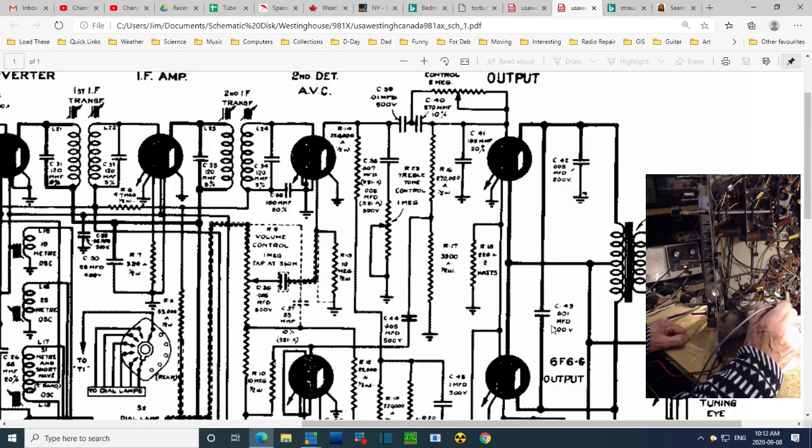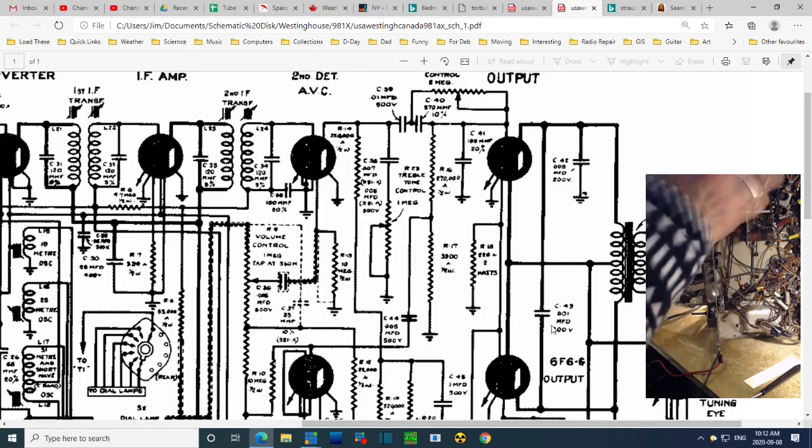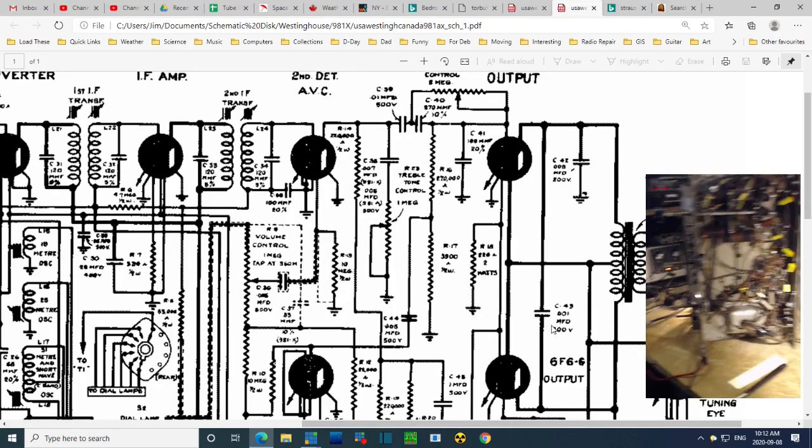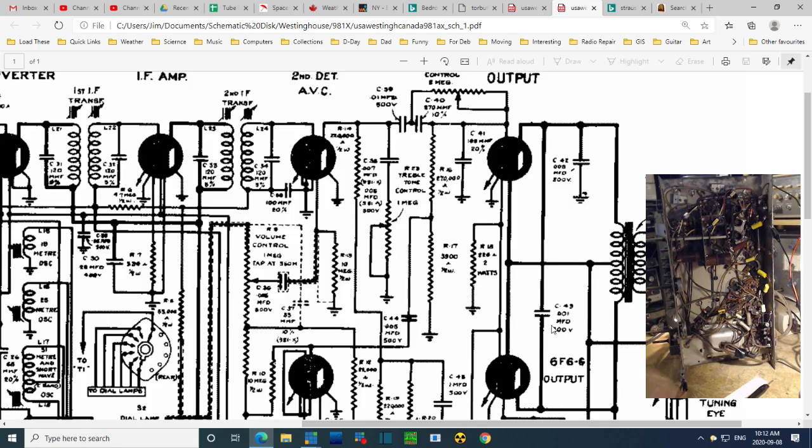Yeah, that's a rectifier tube at the bottom anyway. So either that tube, I could swap them. Yeah, swap them and see it. Hey, bingo! Swap those tubes. See if the voltage flips around. Now, just to be absolutely sure,